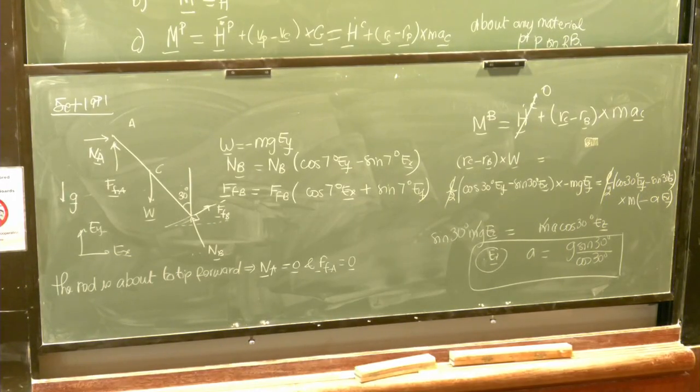It's the vector from where you're calculating the moment about to the point. So RB minus RC. So here I'm calculating the sum of moments of NB and FB. Oh, just like the distance times the force. Yes, but we're using vectors. So everyone, we need to know this. The moment of a force, that's things we know from statics. And if we don't know this, we cannot pass dynamics.